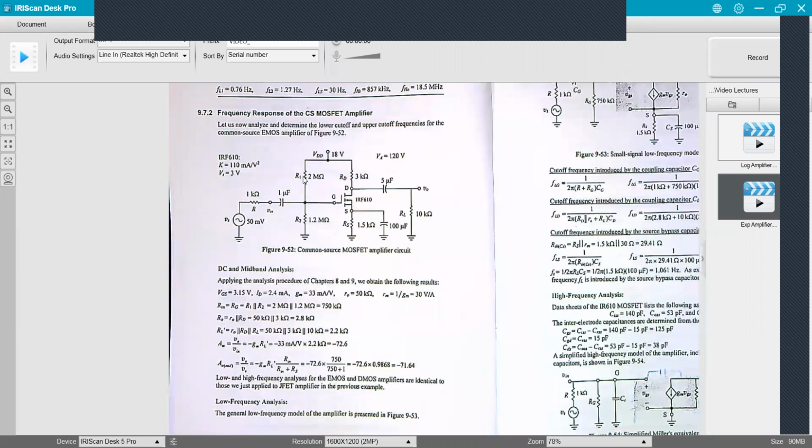The other reason you want to use a larger resistor here is the more current you flow, the hotter your circuit's going to get. Depending upon where this thing might be located, it might be in a place where it can't get any cooling. And so you've got all that extra current just running through those resistors for no purpose other than we just got small resistors. Okay. But that's basically why they're so large. But that's a good question.